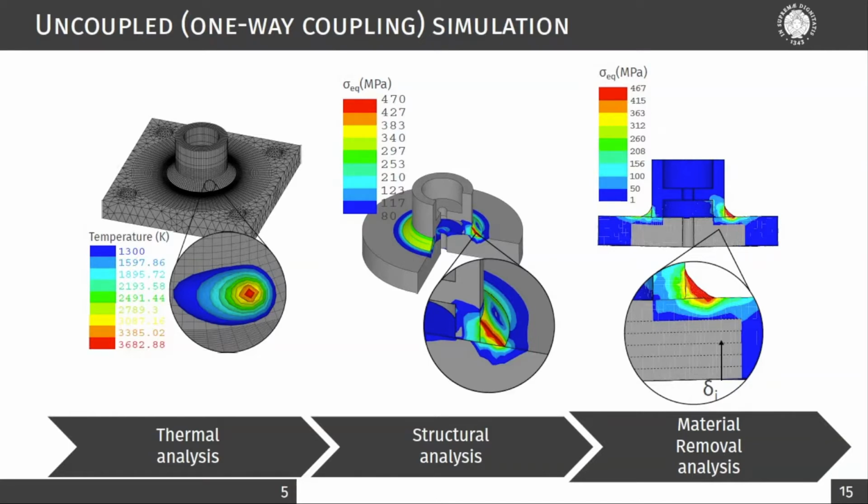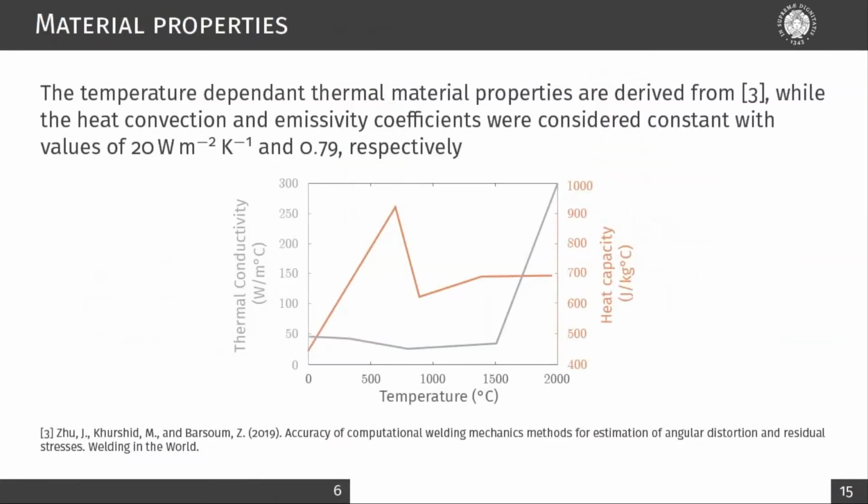The mesh structure has to be the same all over the 3-step simulation. Furthermore, a correct mesh structure was required to reproduce the cutting process through the birth and death method by designing the correct hole geometry upstream. The studied finite element analysis employed a 3D model with temperature-dependent thermal and structural material properties.